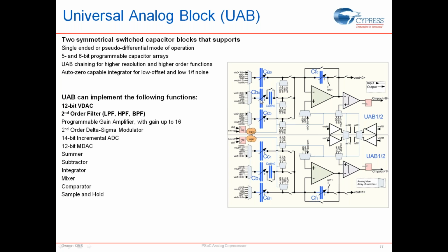If I have an amplifier and I'm switching in one phase for the input, I will have a positive gain. And if I change the switching, as in change the modulation of the switching frequency, then I would have a negative gain. Meaning, if I were to sample in phase 1 on the input side and discharge in phase 2, I'd be getting a positive gain. And if I were to switch that into charging in phase 2 and discharging in phase 1, then I'll get a negative gain. So that can be accomplished by a single bit in this